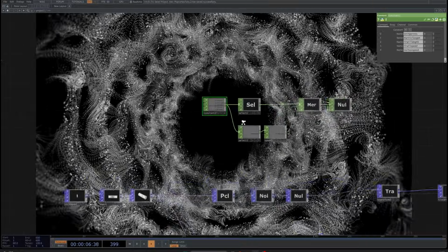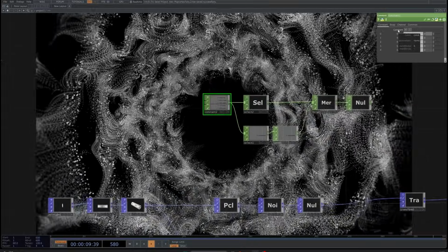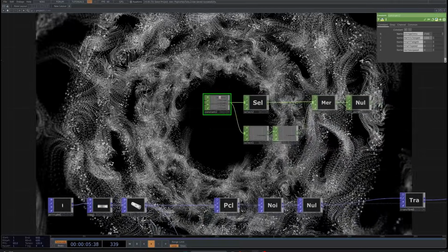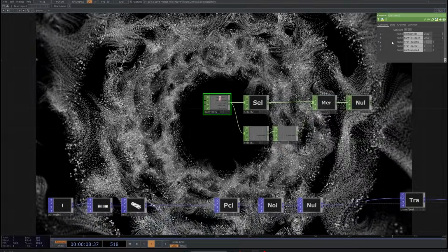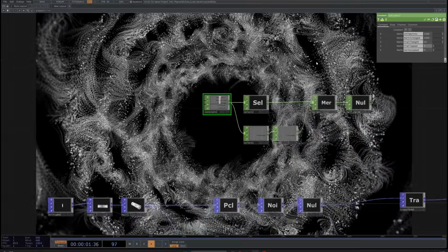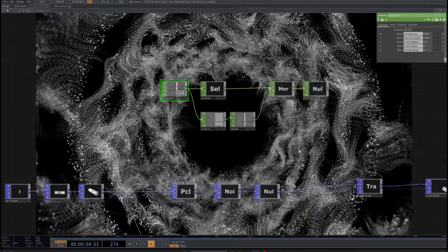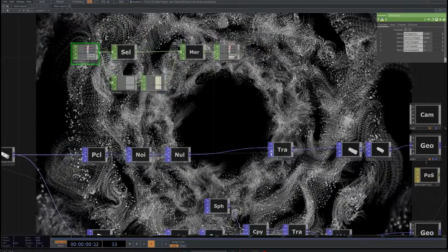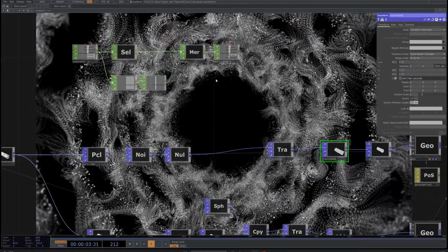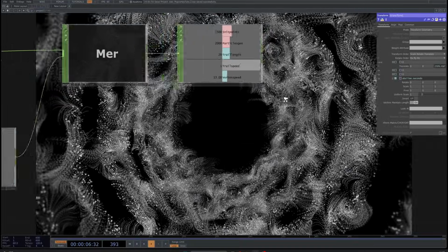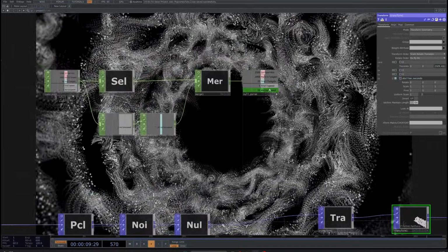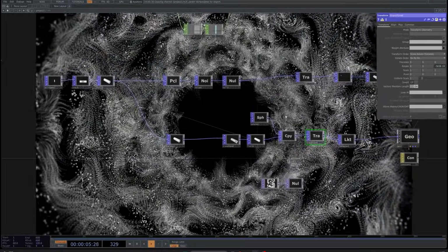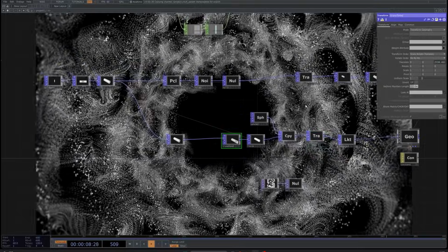So let's choose for now init point, something like 2500. Same for particle generation, or 2000. Trail length, let's choose something like 20. Trail speed, maybe something like 1, and vortex speed something like 1. And we are going to export all these parameters to where they need to be exported. So the vortex speed, we need to export it both to this transform, the transform for the particle trail, but as well the transform in here.